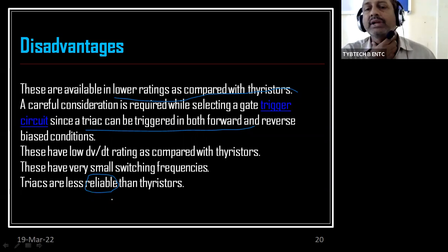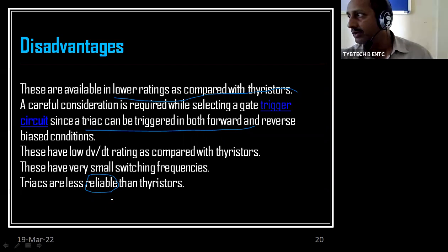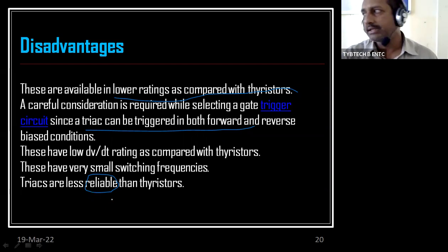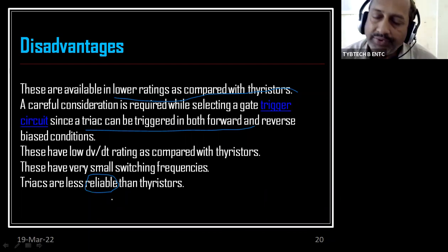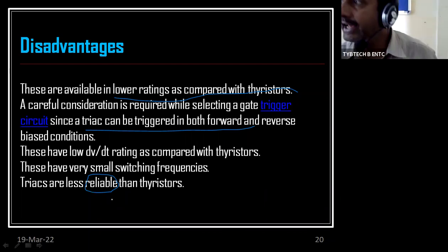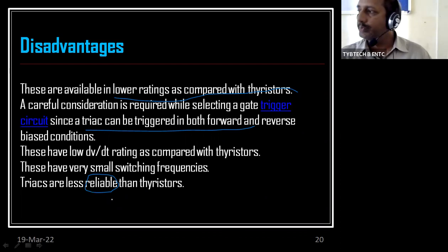So definitely this reliability depends on the parameter, that is the power saving or the power control. Whenever the question comes to power control of AC appliances, SCR can be used, or this triac can also be used. But if it is a high power or high HP motor that you are supposed to regulate, then the triac is less reliable than the other devices of the thyristor family. So these are a few disadvantages of the triac.